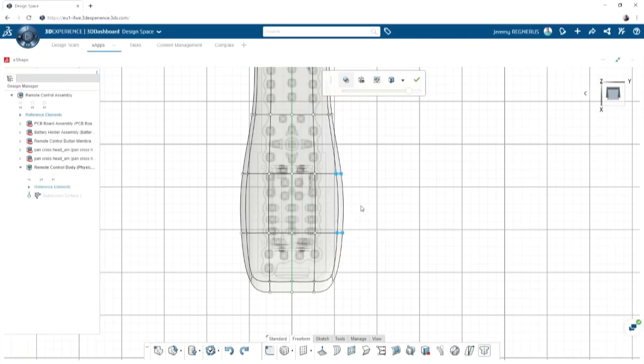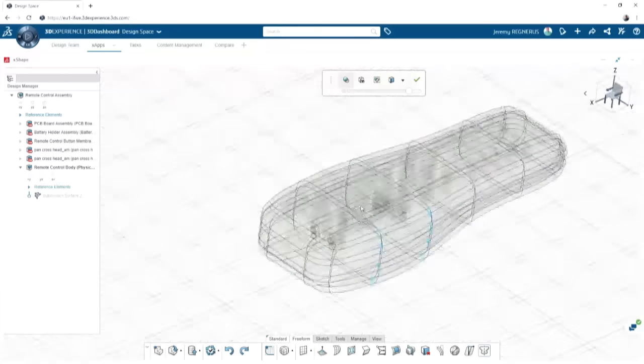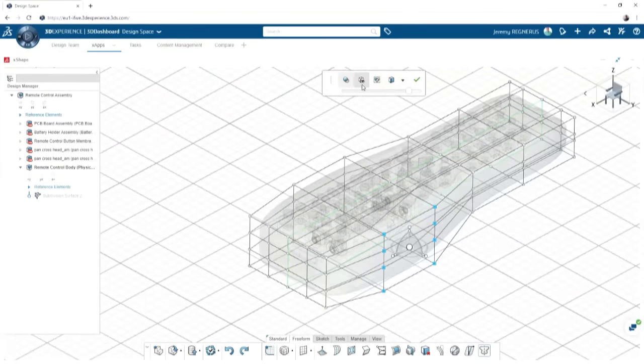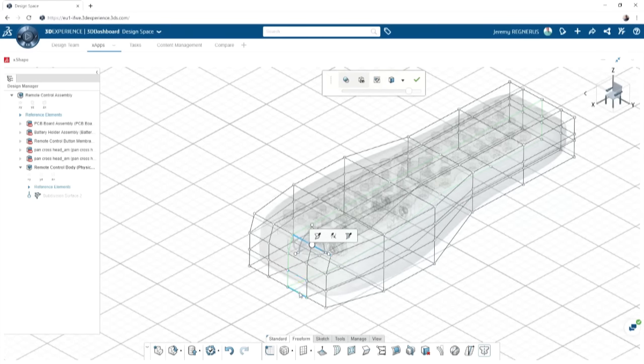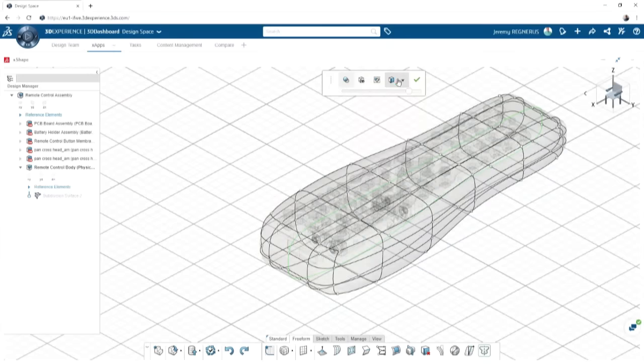So we've been doing some very conceptual dragging, but maybe I want to get a little more detailed and start really refining the shape. I can toggle over to what's called the cage manipulator. This gives me a really fine adjustment to the overall shape, where I'm going to tweak and modify the front part of the shape. We'll make a few last-minute changes here, but one of the things we want to start thinking about is where that landing pad, where my thumb's going to go, should be.